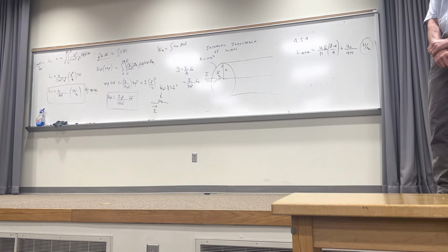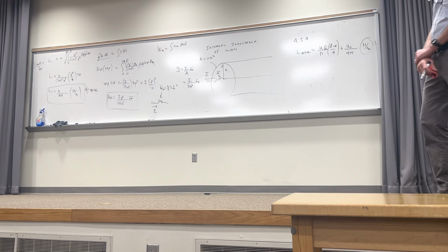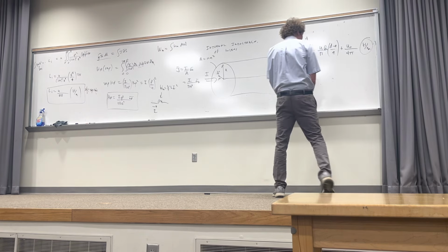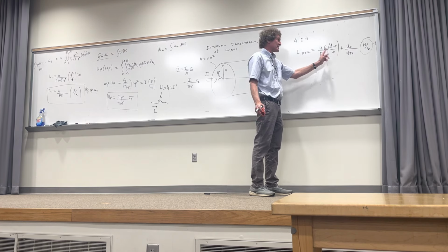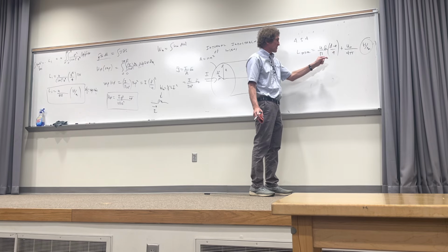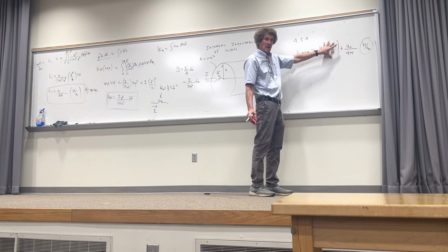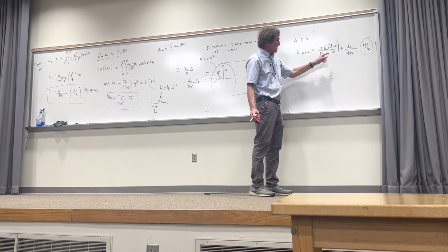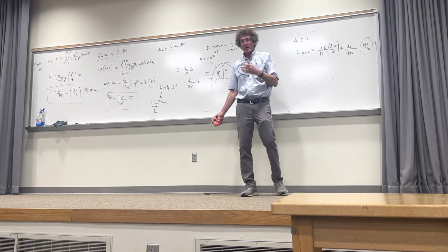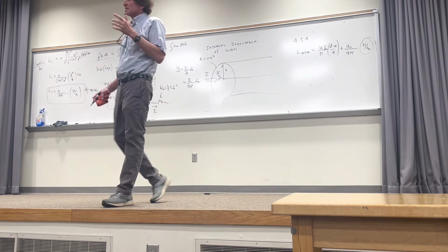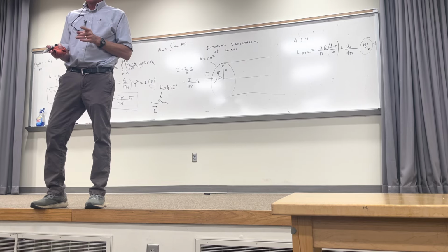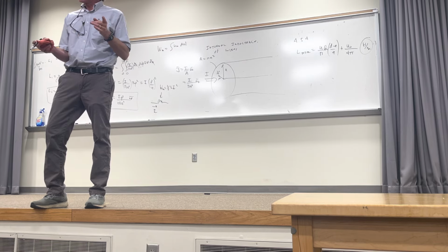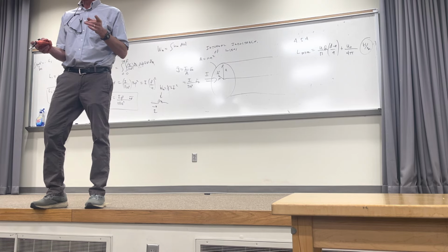Yes. All right, but I have one comment, and this is important. Just for a second, think about the ratio of this to this, or of this to this, better yet. All right, if you get rid of the mu zeros, get rid of the pi's, this is 1/4 this right off the bat. Do you agree with that? Now, the natural log of B minus A over A really is proportionally how much? So the self-inductance, or the external inductance for this wire, it starts out being 4 times the natural log really of D over A.